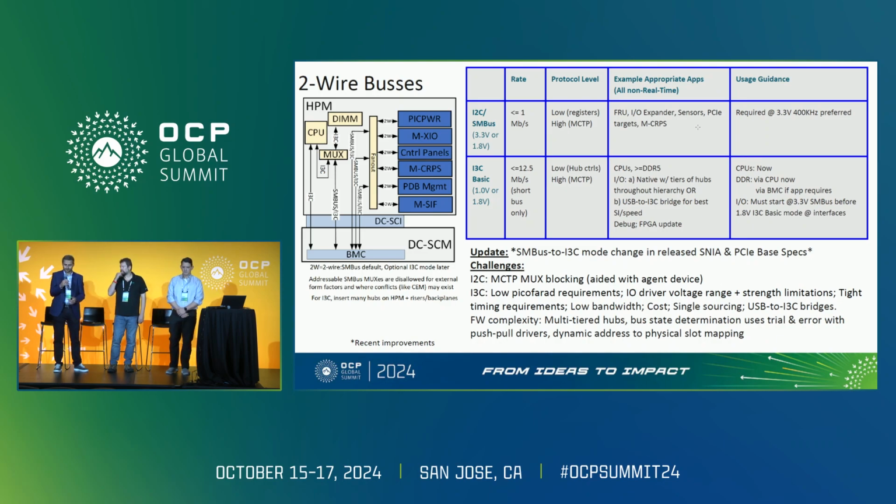I3C is posing serious challenges on the signal integrity side, on the system designers, on your routing lane. The designer needs to look at the buffer strengths of your devices, the total capacitance of the bus, and all sorts of those aspects that they simply didn't care that much about with I2C interfaces. And eventually the bandwidth is not that high, right? The bandwidth that we are seeing in effective use cases is not delivering what's been promised.